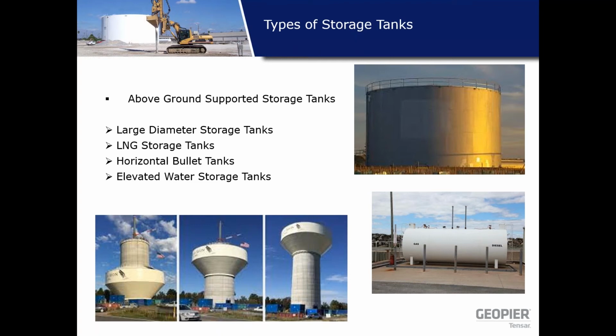large diameter storage tanks, what you see on the upper right hand side, about 200 feet diameter steel tank, which is typically supported on granular pad or ring wall foundations. The flexible floor system of the tank generally has some asphalt or sand underneath for containment reasons.